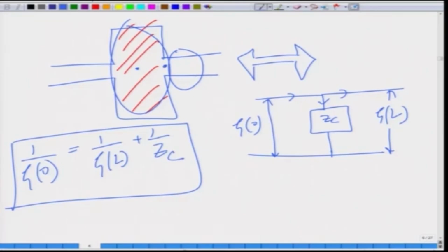In other words, the lumped element behavior of a tube is a function of what lies downstream of it. To summarize this discussion, if the tube in question is much smaller and thin and sandwiched between two tubes of much larger cross section, that is two larger cavities, then it behaves like an inertance. On the other hand, if you have an acoustically small tube, k naught L much smaller than 1, sandwiched between two tubes of a much smaller cross section, that is, an element with a much smaller length but a diameter much bigger than the elements upstream and downstream, then that element behaves like a compliance with a shunt impedance.